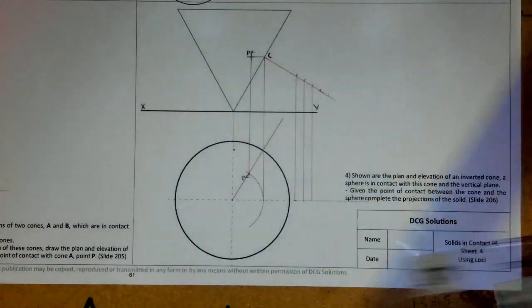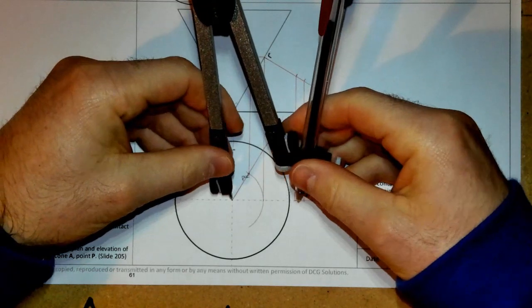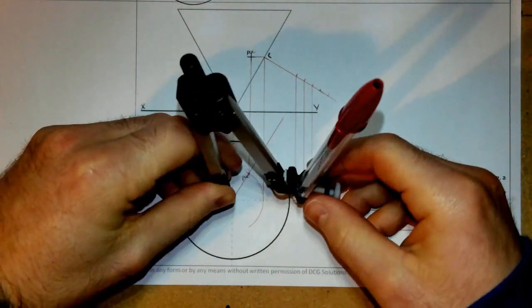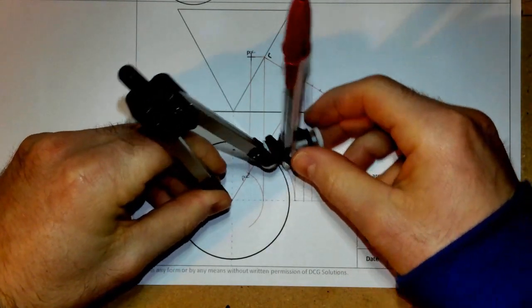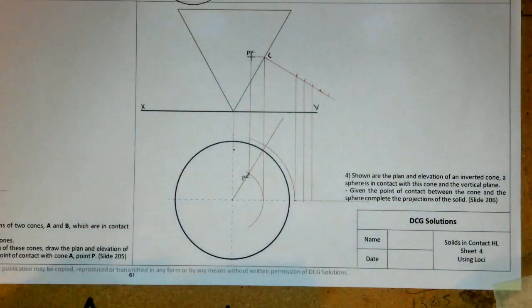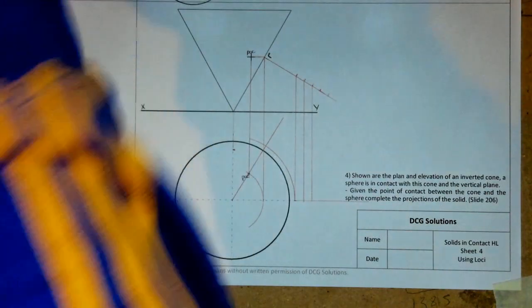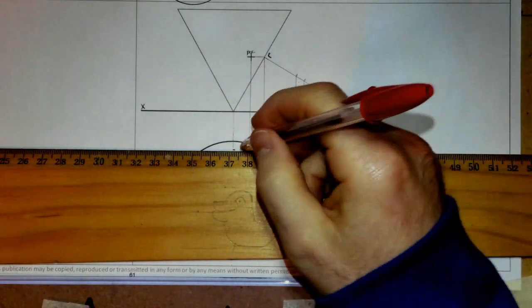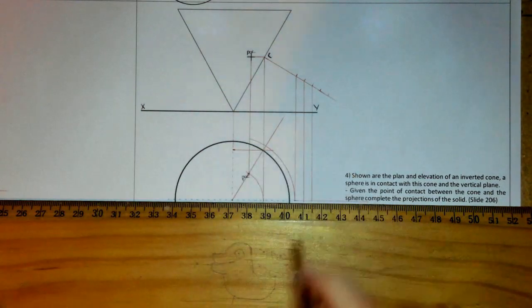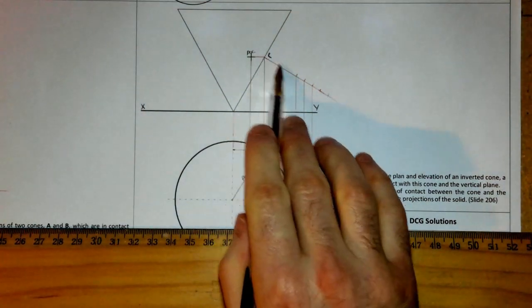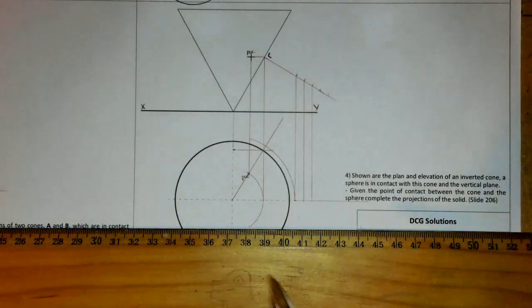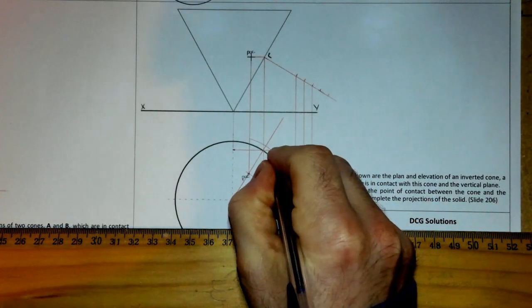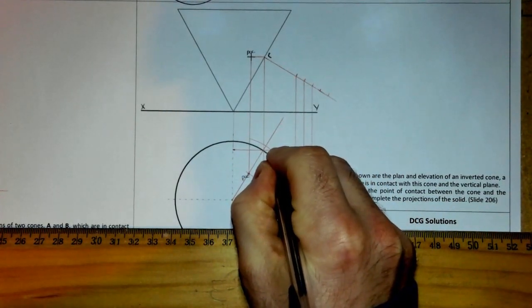And what I have to do now in this position is rotate the very first one, which was the 20. I'll rotate it up like that. And then where that rotates up, I'm going to mark out 20 like that, because this distance out here was the same distance down here. So I've now found a point on my locus.